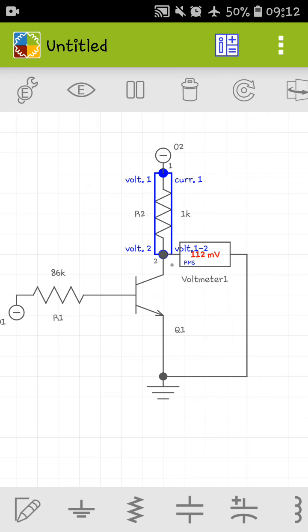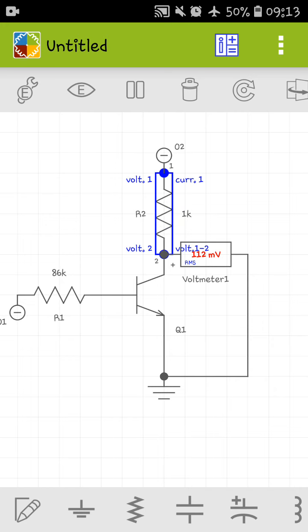When the current through the collector is 0.005 ampere, the transistor must be in saturation. It means the voltage between the collector and emitter is 0, so all the voltage must be dropped in this resistor when the current is 0.005 and the supply is 5.